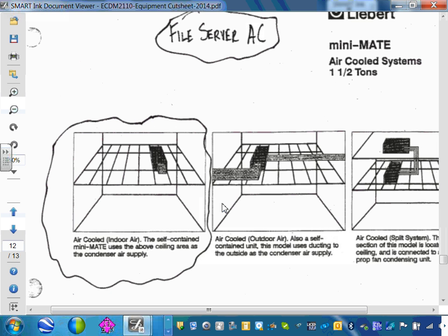We don't know. When it comes to mechanical equipment, it's specified by mechanical engineer guys. Then they give you a list or a cut sheet like this. They call it mechanical schedule or mechanical cut sheets. And from this information, you size the branch circuit, the disconnect, and the overcurrent protection device. And the control, you have to decide.